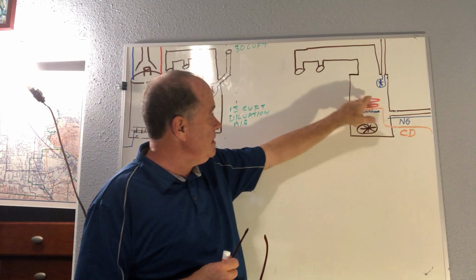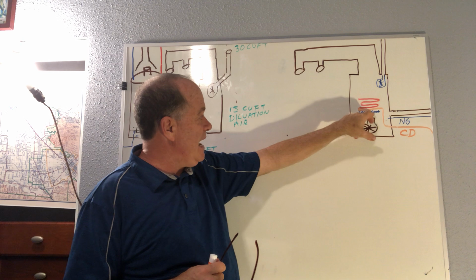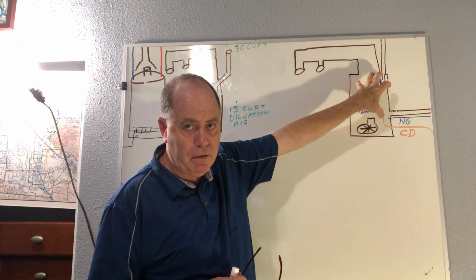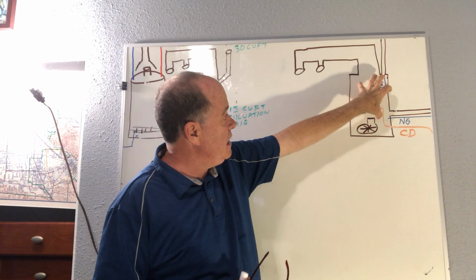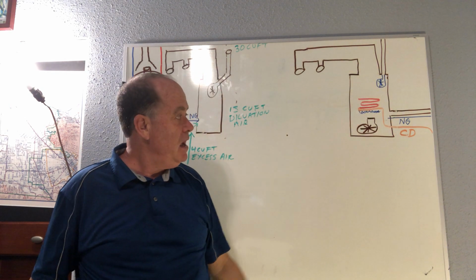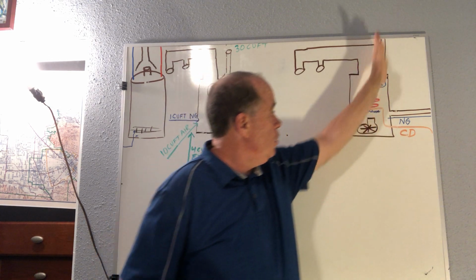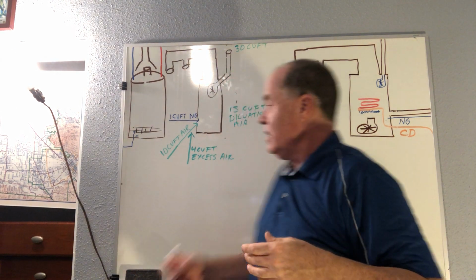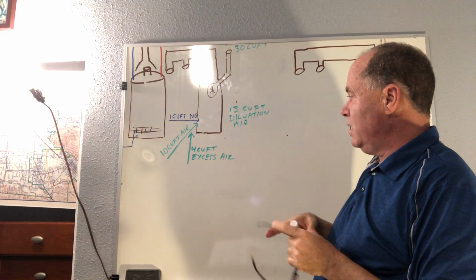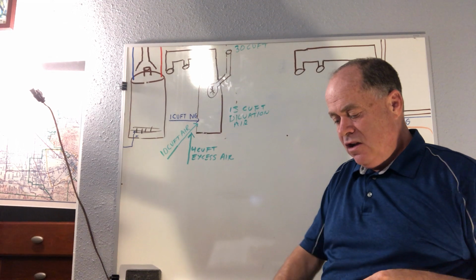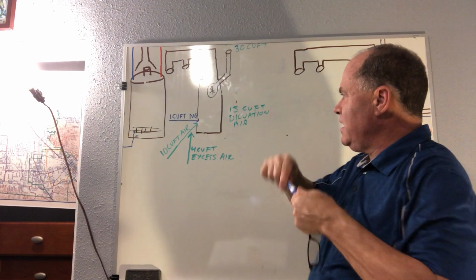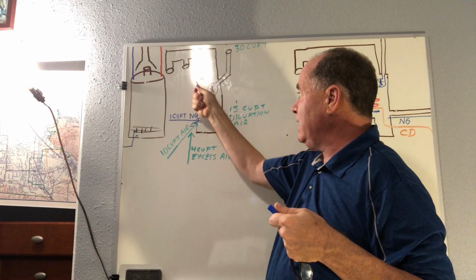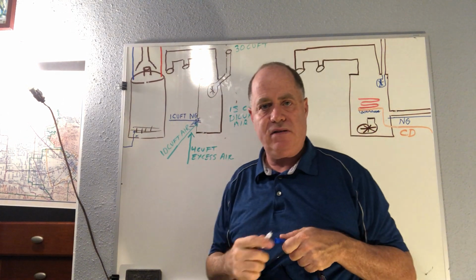And then all of this inside, the power venter, the gas valve, the heat exchanger where you see the blue flame, this is all kind of sealed up, kind of hard to work on. It's like a sealed chamber. So the air that comes in goes out, and we're not relying at all on the air around it. And you'll even notice that with these type of furnaces, you'll see a lot of little air vents sitting on top and on the bottom, and you'll see people piling things up, blocking the air vents.